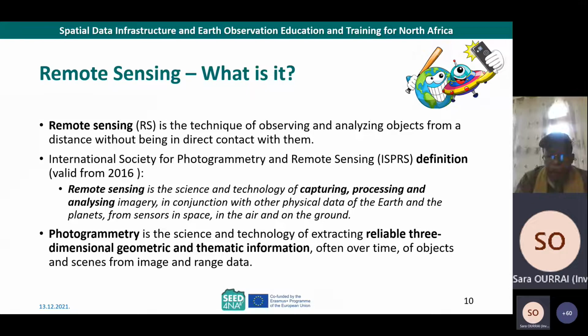And in remote sensing, how could you be accurate with a pixel of 30 by 30 meters? It's a 900 square meter pixel, and everything that can be seen on the Earth's surface in those 900 square meters, a car, a human, a building, a road, whatever, all of that information gets just one pixel value. So that is the real distinction between photogrammetry and remote sensing.